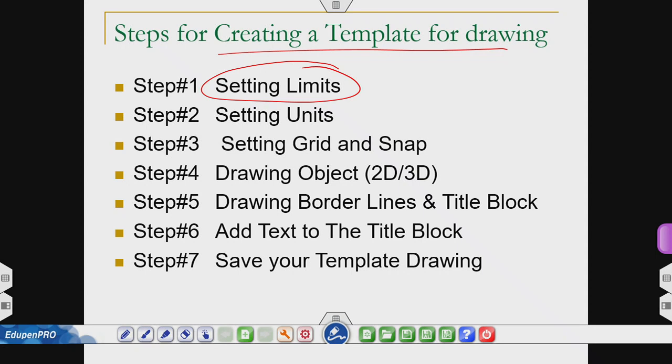But when we take the drawn object somewhere, like exporting this data, or going for print, we cannot print such a big page. So first we set the limit of the page, meaning what our drawing area will be. We are setting the page coordinates, meaning this much area we are limiting for drawing purposes. So first we are setting the limit.